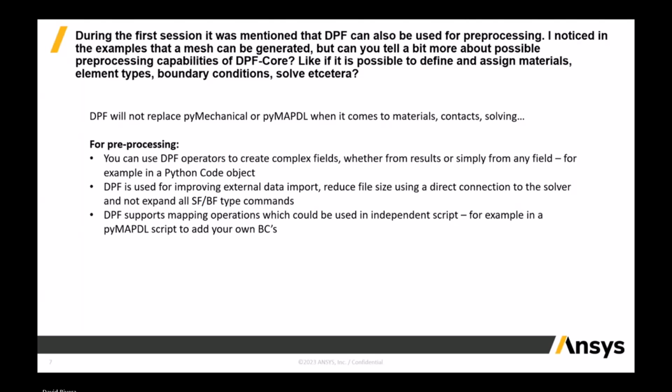On our end, we are also using DPF for pre-processing when we do external data. So you will see many changes. Some have started with 24R2, but we are doing way more with 25R1, where instead of writing all of the SF, BF type of commands to the APDL file, we are going to use DPF as a way to extract the data at solver time from a file, which will reduce that.